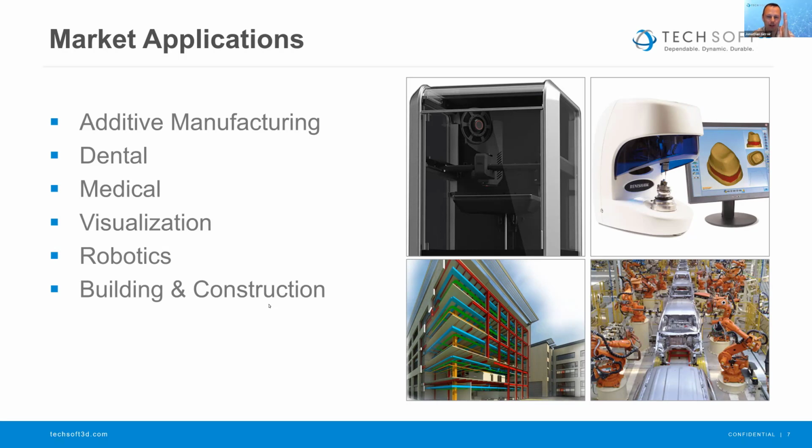You may have a structural pillar that is being intersected with some HVAC ducts, and that can't be built. So you have to create an engineering change order, tell engineering, hey, you've got to reroute this. Those intersections can be very easily calculated using Polygonica, given the data that exists in the model. So being able to figure out those clashes and provide a list to the users in their software very quickly is another use for the markets.